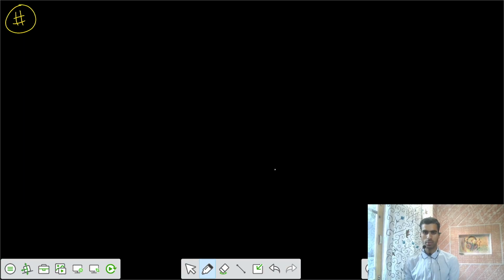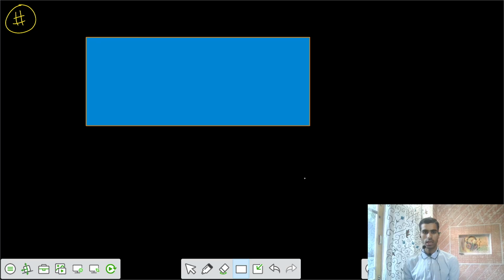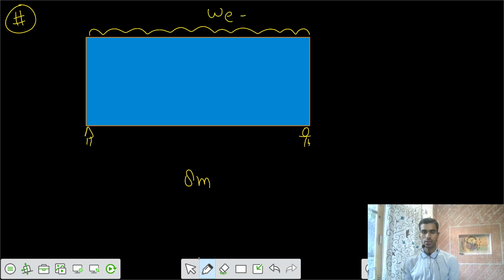So we have an 8-meter beam, simply supported. Live load plus dead load is there. Let's write the external load as equal to live load plus dead load, and that total is 1.57 plus 2.50. The sum of these two is this much kilonewton per meter.